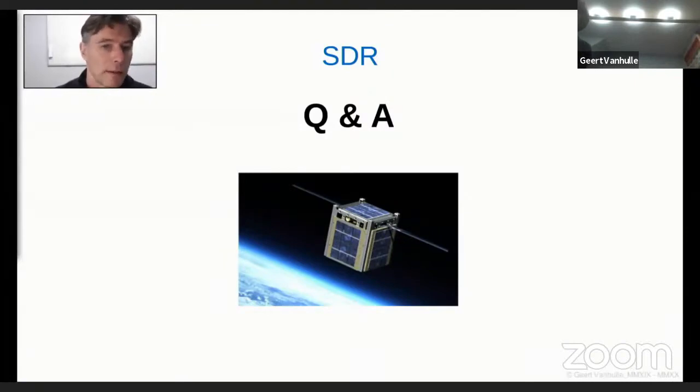So how do you deal with that? The problem is, once this kind of amplifier starts oscillating, the noise at the input on that frequency is sufficient to trigger that event. If we take the harmonic signal in the output signal, which is maybe an easier example to understand, instead of filtering the output signal, what we can do, and this is the huge advantage of software-defined radio, is in the digital processing, we add the inverse signal of this harmonic digitally to our sample range.